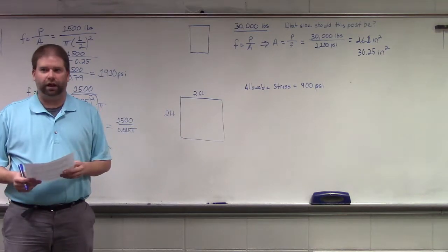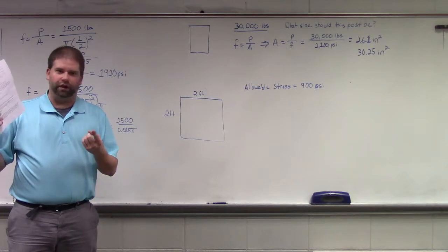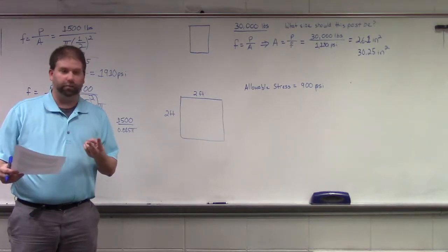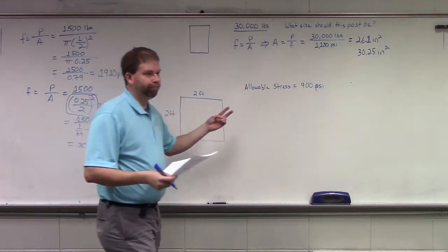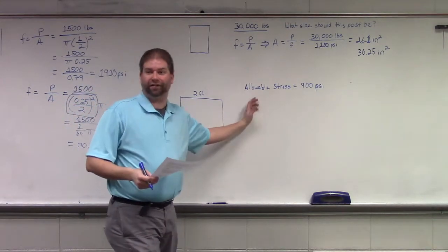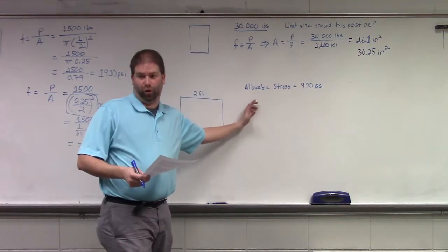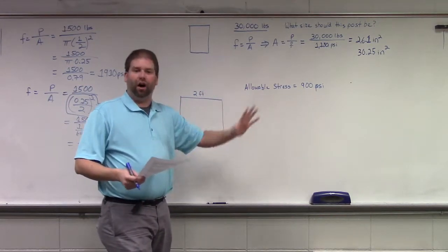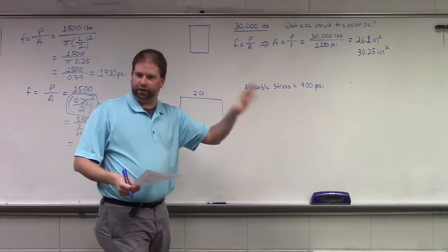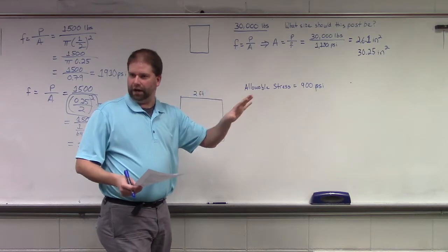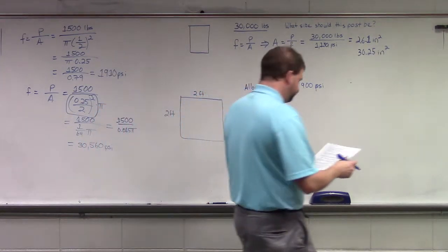We're going to get things like chloride ion migration, freeze-thaw durability issues, possibly coming out and having to epoxy things, maybe having to come out and core this thing at some point. All sorts of things where we're going to have to get a third party out and investigate this system and see what's going on. So we don't want to allow ourselves to get too close to this.